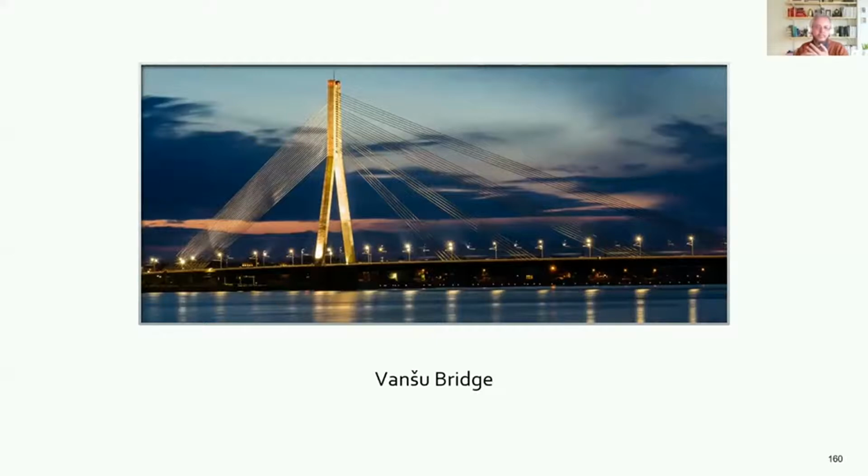Basically, with these sorts of structures, in general, the chance of the wind uplift overcoming the self weight of the deck is slim. But if you were to analyze the wind and the self weight separately, you'd analyze the wind without the self weight, and suddenly the bridge deck would span from support to bank, and that would be nonsense.